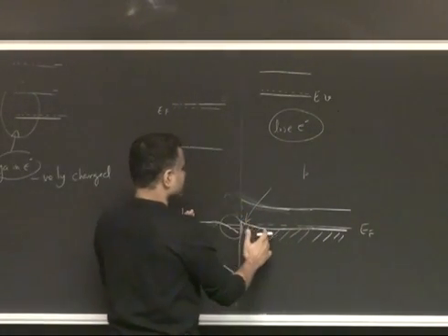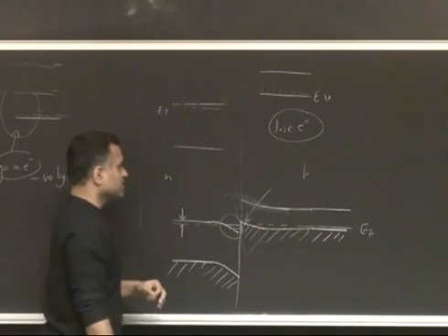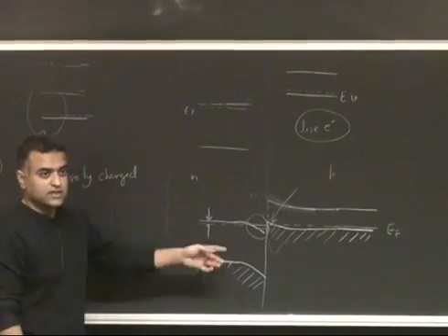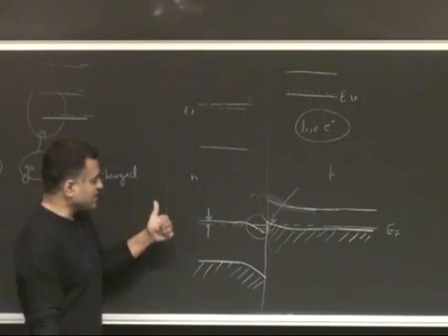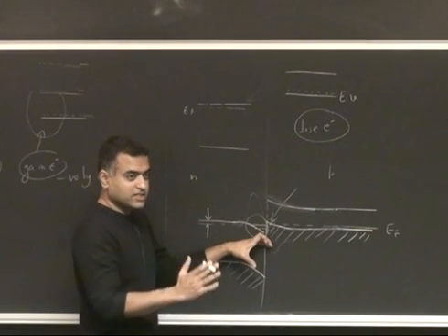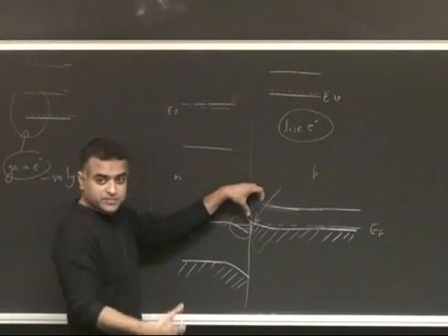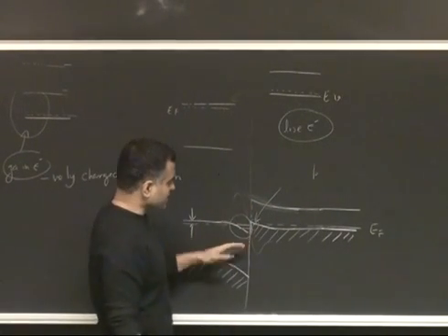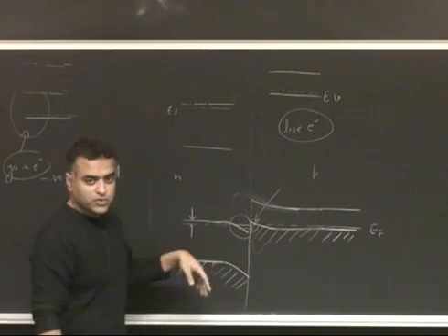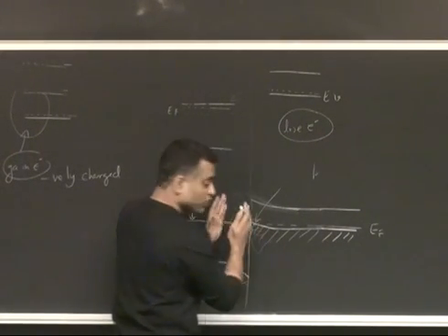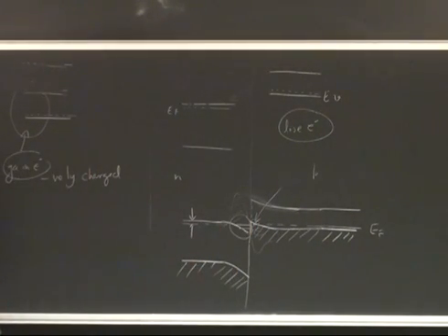So what happens here is, this is a very weird p-n junction. In a p-n junction, we learned earlier, in a homojunction, you have depletion on both sides, right? Here you have accumulation on both sides. What is accumulation? The n layer has become more n-type. It has accumulated more electrons at the junction. The p layer has become more p-type. So it has accumulated more holes on the p side. Right? This makes sense. So you have a dipole here, but this dipole is a mobile dipole. Basically, the extra electrons and the extra hole gas here are both mobile. Does this make sense? So this is a slightly different sort of heterojunction.